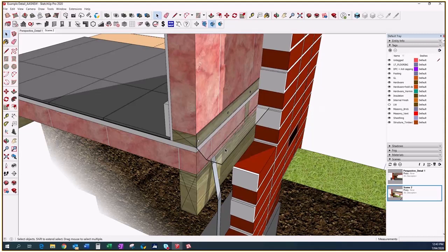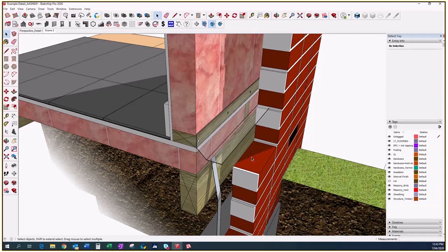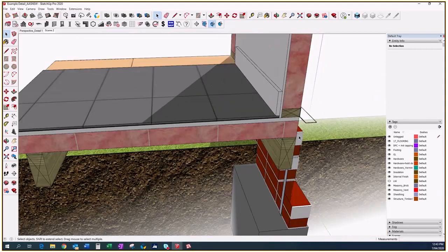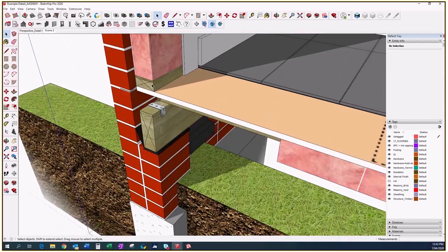So inside of SketchUp at any time, you can not only create a layer via what it is, masonry versus hardware, footings, flooring, whatever it may be, but you can also have your entity info, so that when you are drawing in there, it will tell you IFC categories, it will tell you what kind of brick, what size joist you're using. All of that metadata is essentially what BIM is. And SketchUp does that. It just doesn't do it in any forcible way. It's really up to you to create your own system.